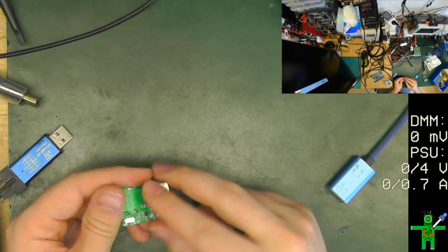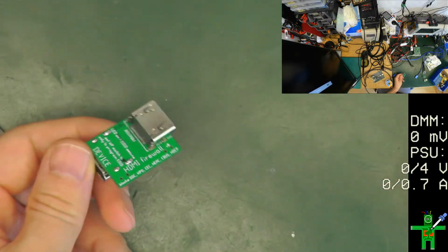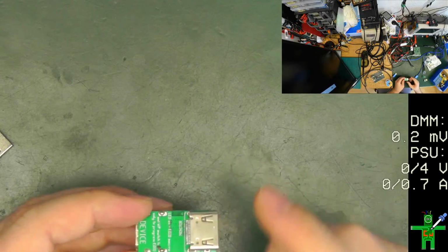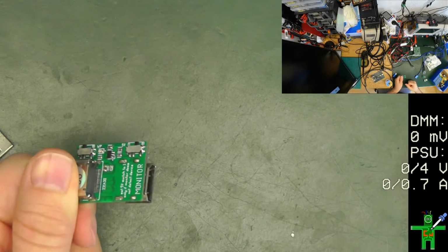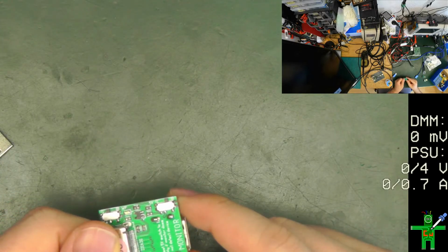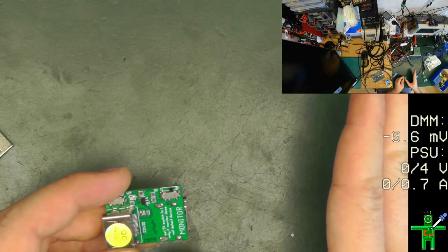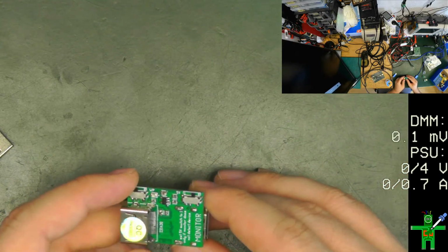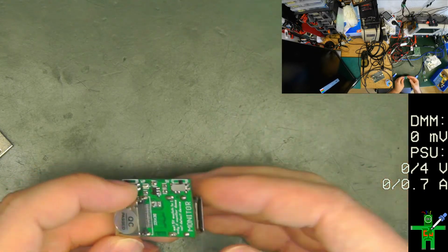Yeah, version 0. This works perfectly fine, although it was radiating a bit much. The issue is that this is not manufacturable because you have connectors on both sides. So not a good idea. It's easy to design. I just wanted to design by hand, and I was not familiar with routing high-speed signals. I didn't route any high-speed signal. The most I did was USB 2.